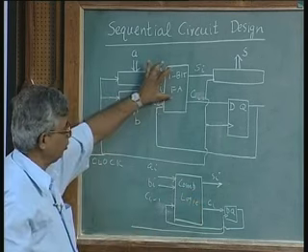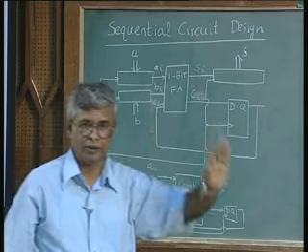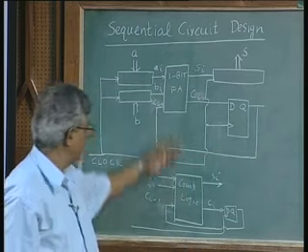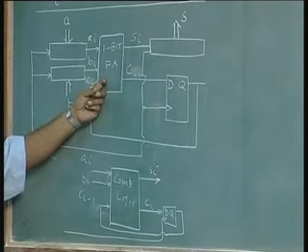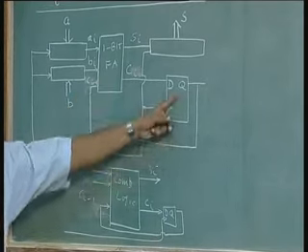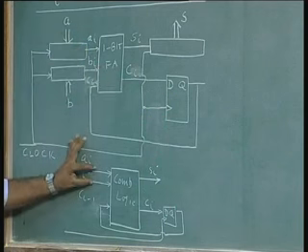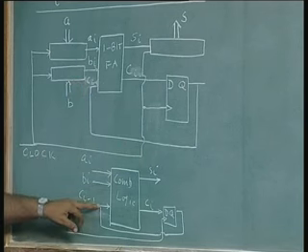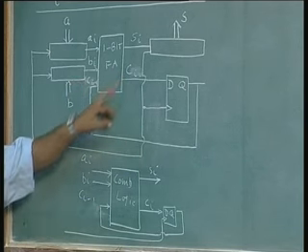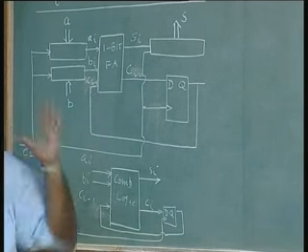Here in this case the 1 bit full adder is a combinational logic, and all of you know that the 1 bit full adder is a combinational logic with, as I said, 2 exclusive OR gates, 3 2 input AND gates and 1 3 input OR gate. And then the flip flop here: the combinational inputs are Ai, Bi, the combinational output is Si, the state variable input is Ci minus 1, and the state variable output is Ci. To give this one exact mapping using a very simple concept, I brought this today.